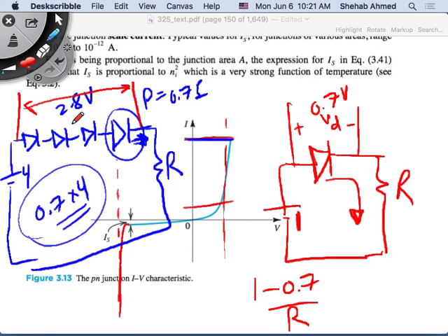It's a voltage regulator. Sometimes, let's say you have this AC voltage. Do you see the lights flickering sometimes? Not fluorescent lights, but the incandescent lights. You will see them flickering sometimes at home, right? Why? Because the voltage magnitude is not fixed. If you are in a hospital, maybe the lights will allow it to happen, but do you want that to happen in cardiac support equipment? You don't. So cardiac support equipment will be interfaced to the power supply using a voltage regulator.